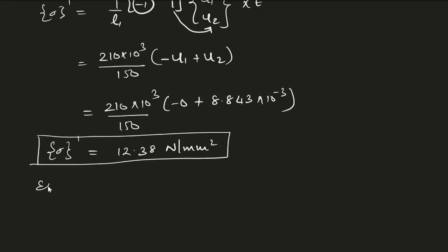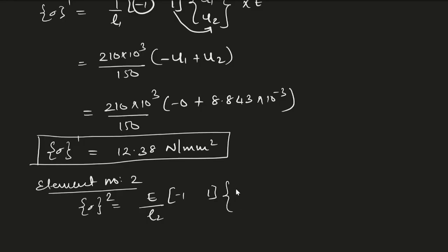Now for element number 2, the stress will again be E divided by L2 into minus 1, 1, the second element lying between nodes 2 and 3.